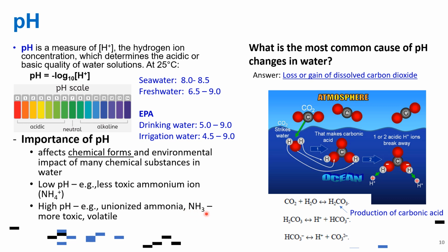So you strip the ammonia by adding some air to strip out the ammonia from the system. That's why we have a stripper in the water treatment system, so that volatile ammonia will go out of the system and you are decreasing your nitrogen content. Or air stripping, or by aeration.